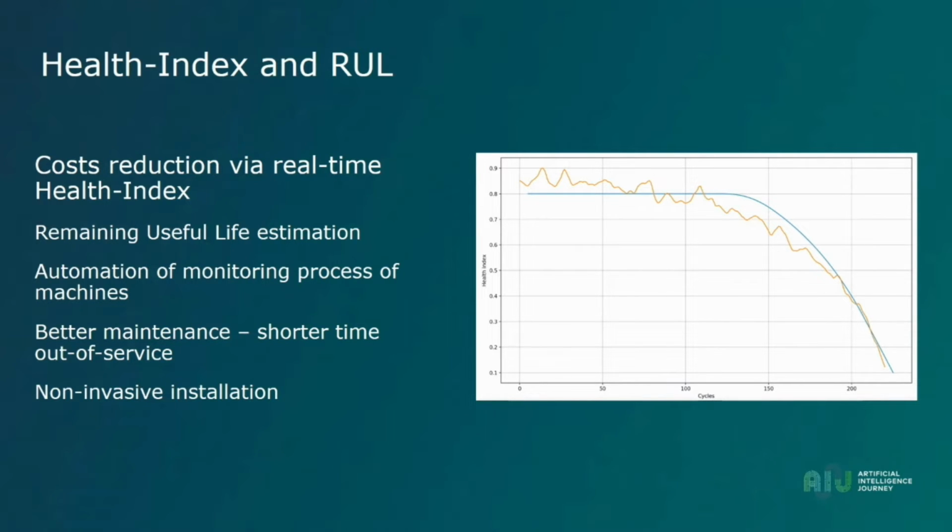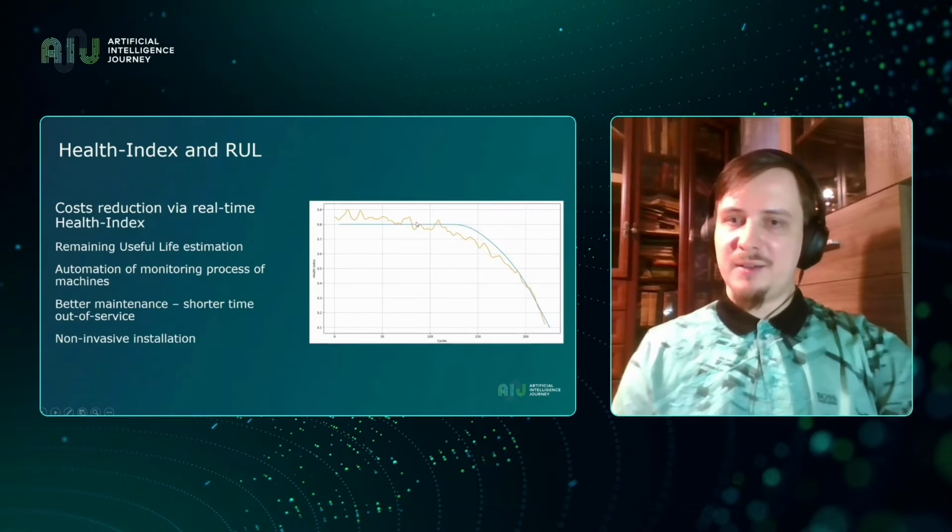If we maintain too early, in order to improve performance or to reduce depreciation of equipment, then it will cause downtime as well, time out of service. So it's important to find this balance, to find the balance that is optimal. And we can use predictive analytics here in order not to have too many false alarms and to have data that will be reliable to maintain equipment.